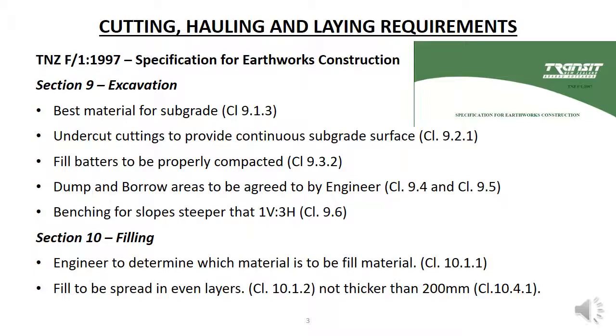Undercutting involves cutting below the designed formation level. In other words, soil is removed and then replaced with other soil. We'll look at that more in a minute. Fill batters need to be properly compacted. Fill batters are slopes on a fill embankment. You may recall from the earthworks introduction topic that we usually need to overbuild fills to allow us to compact the soil right up to the edge. That will be the surface of the batter. Then we trim back to the design batter.